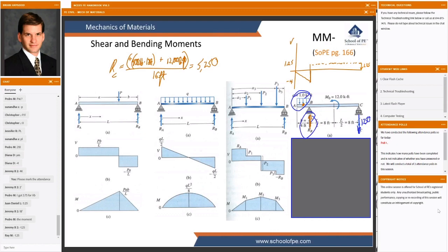If you looked at that shear diagram, would you have noticed that there was a moment applied to this beam somewhere, like an applied moment of 12,000 pound-feet? You might not have noticed. You don't really see it explicitly listed there. Obviously, it affects our reaction force magnitudes, but it's kind of hard to visualize that applied moment just by looking at the shear diagram. All right, well, what's our moment diagram going to look like?